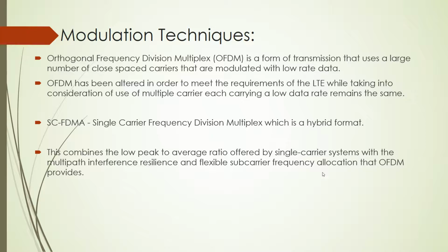SC-FDMA, single carrier frequency division multiplex, which is a hybrid format. This combines the low peak to average power ratio offered by single carrier systems with the multipath interference resilience and flexible subcarrier frequency allocation that OFDM provides.